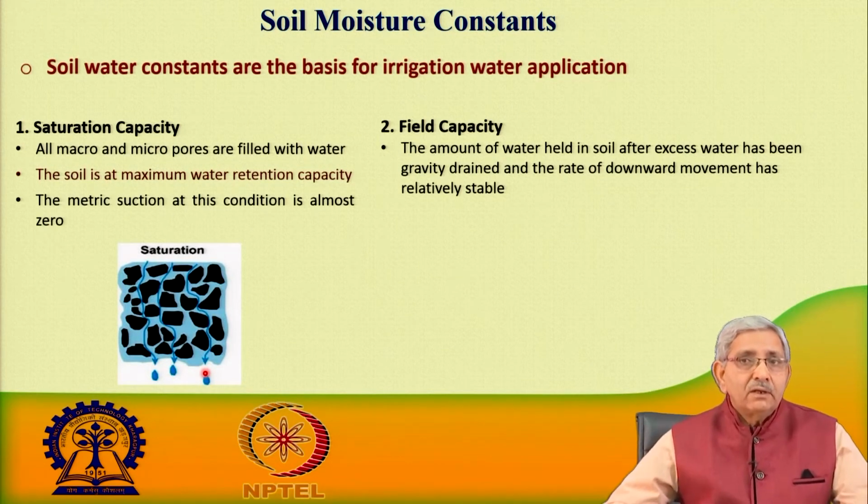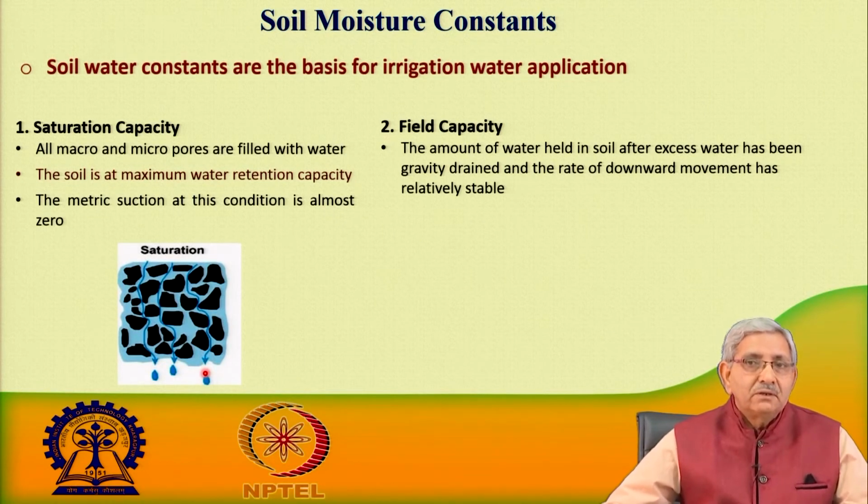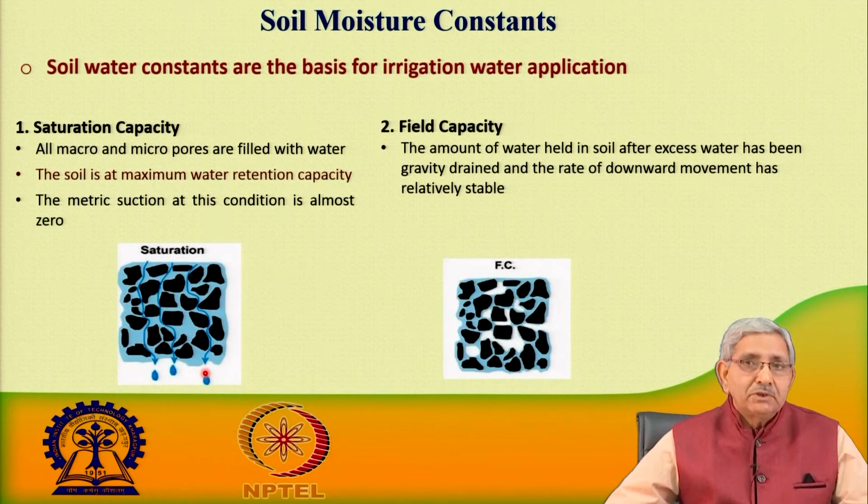It depends on the type of soil. If it is a clay soil, it takes more than 48 hours, even 72 hours. If it is a very coarse soil, a sandy soil, it takes only a few hours, maybe 6 hours itself. So, that depends on the soil texture. At field capacity, the water is drained and part of the pores are filled with air and water.